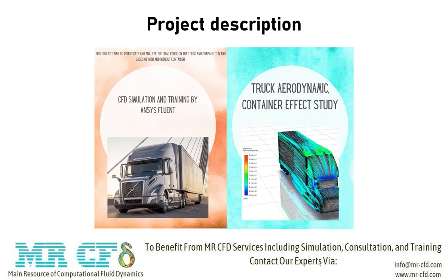In this tutorial, we're going to show you how to first create the geometry related to the project of the truck aerodynamics. After creating the geometry of this project, we're going to import it into the ANSYS meshing software in order to create tetrahedral mesh cells over it. And after that, we will start the Fluent software and show you the needed settings in order to perform the aerodynamic simulation and investigation over the truck geometry.